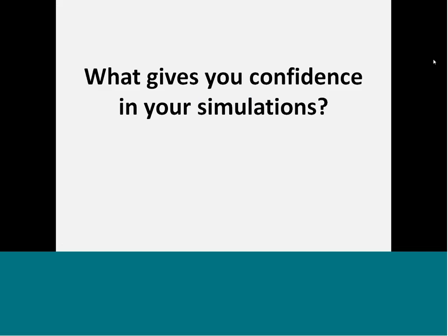So what gives you confidence in your OpenSim models? And we generate this confidence probably in several different ways. I mean, the first step is probably just getting the model to converge. You know, not having the knee behind the head in the kinematics, and then obtaining reasonable muscle forces when we look at our plots. And so many of us have systematic processes in which we perturb our models, and we find out just how robust that is.